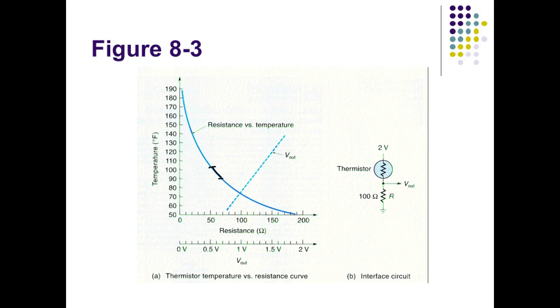So if I've got a thermistor that's sensing the temperature of a motor, we can make sure it trips at a certain temperature, right? You understand? So it could be exactly accurate. A lot of your motors have thermistors in them. If you've got a single phase motor, a low horsepower single phase motor, like you've got a lot of those in your house, those guys have thermistors in them. But they're thermistor switches. So what they do is they switch when they get up to a certain temperature, right? You understand that? Thermistors are very, very popular.